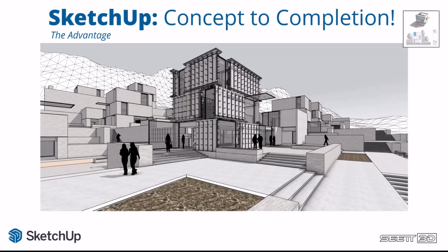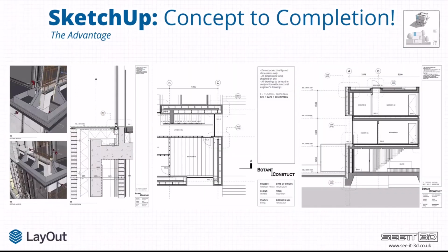This stage reveals technical details, including wall construction, hangers, and 3D components, ensuring the model clearly communicates buildable design intent. Technical details, dimensions, and references are prepared in a CAD-like style using LayOut. Detailed 3D models are also included to clearly explain build requirements, ensuring precision, understanding, and well-designed solutions while avoiding unforeseen problems on site.